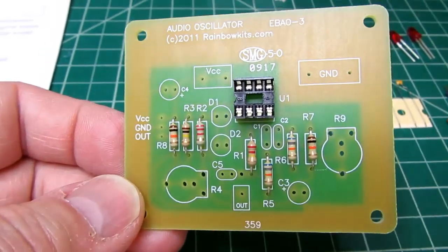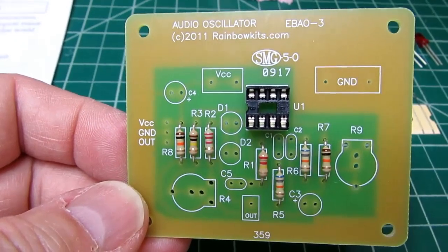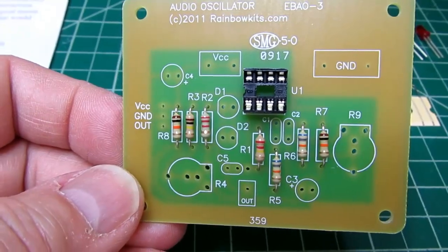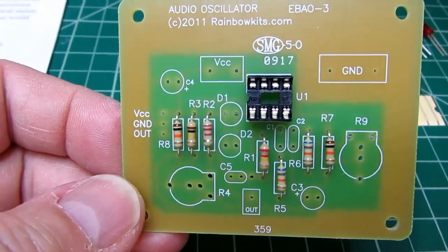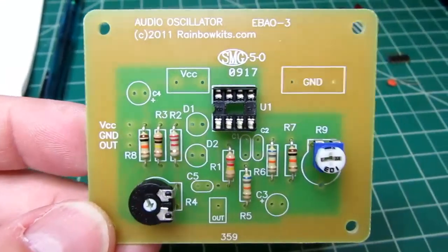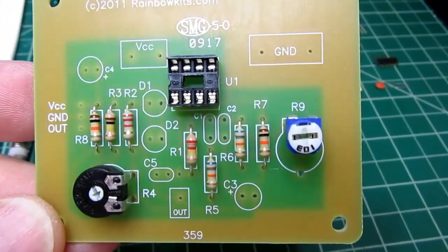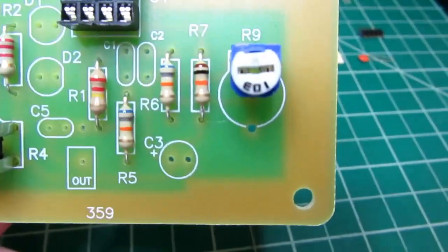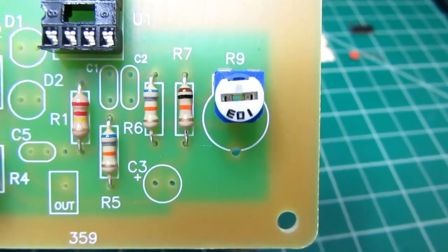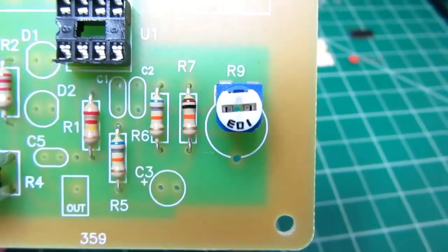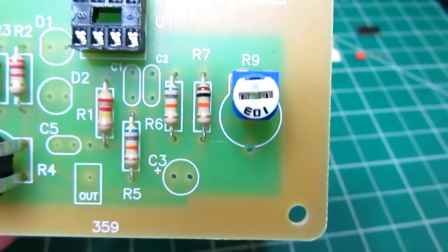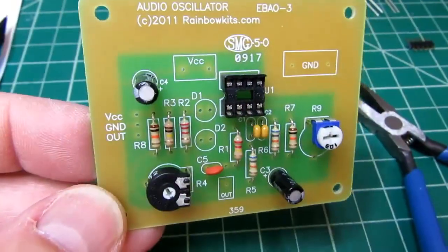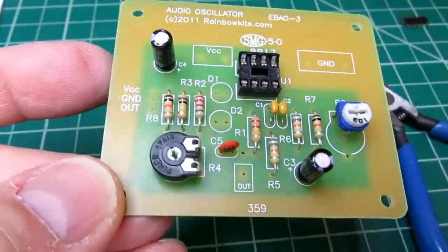All the discrete resistors are on the board, and the IC socket. I put that on first, even though the instructions don't mention inserting it till nearly the end of the process. And now the two trim pots. Interestingly enough, the kit instructions say there should be a 5K ohm pot here, but the part is marked 10K. They didn't make any allowance for the part substitution in the instructions. And now all the capacitors.